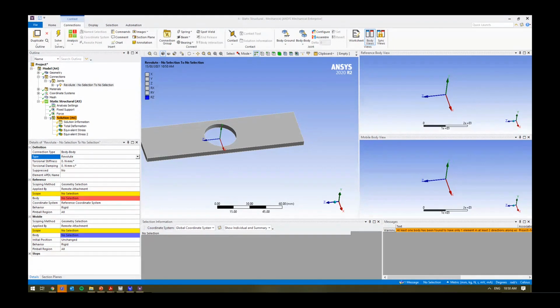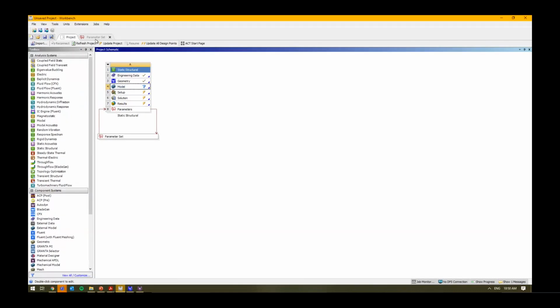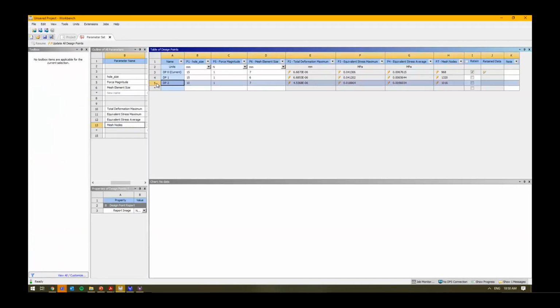Cool. So another question about parametric analysis. If it's huge and it's taking too long, is there a way to manually solve? Yeah, so we can in the parametric analysis. We can, if you wanted to, right click on something and just update the selected design point as well.